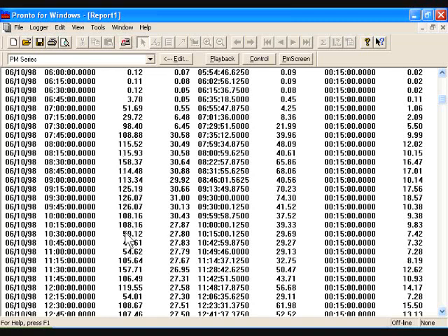And you can see that you had over 100 kW demand until about 10:30 in the morning, and then a drop until 11 o'clock. So that's probably early lunchtime or break time or whatever. Then if you continue on down, you can see at 12:15, that 15-minute period, for some reason, maybe a portion of the assembly line went offline, or they stopped it to retool or reset, and the demand went down to about half.